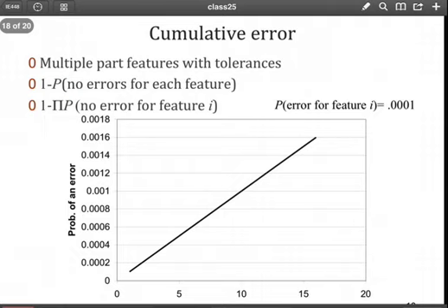Of course, how do you reduce your type 1 and type 2 errors? The only way to reduce that is to decrease the tolerance on your gauge specification. Of course, as you do that, the cost of your gauging goes up, but your corresponding manufacturing costs and type 2 error costs are going to decrease, so it could have definite benefits.